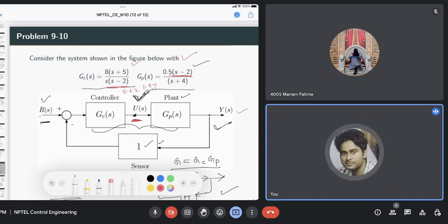Or if the system parameters change, like for aging or some effect after some time, then this pole location will change, right? Because this physical system will change somehow, due to the effect of temperature or the environment. For the plant also, that is applicable. For the plant also, this pole location will change. So then also this exact cancellation will not occur. So it's not a good option to cancel this right half plane zero or poles by placing them in a cascade, right?